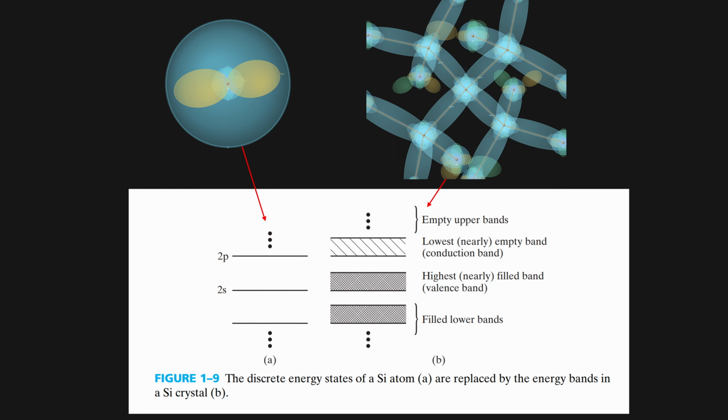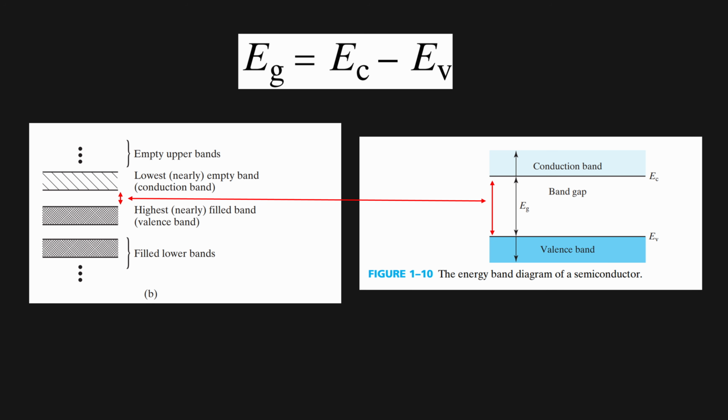The subshells of individual atoms are described as discrete electron energy states. When the atom is in an excited energy state, an electron can occupy higher energy levels. When combined into a crystal, the electrons are shared between atoms, and the electrons cannot share discrete quantum states with the same spin and energy and orientation. So the electrons occupy a wider continuum of energy states called energy bands. The highest energy nearly filled band is called the valence band, beyond which is the nearly empty conduction band. The difference between these energy bands is the band gap, and electrons cannot occupy energy states within this gap.